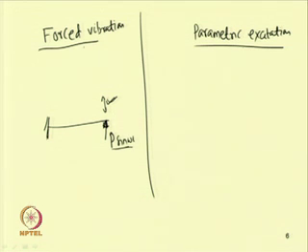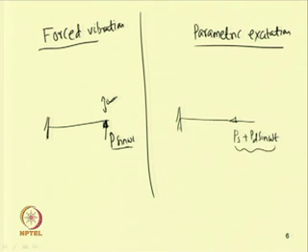But in the case of a parametrically excited system, let us take the same cantilever beam and apply an axial load, P s plus P d sin omega t. As we are applying an axial load to the system, if it exceeds the Euler buckling load, then it will start buckling. But when a dynamic force acts on the system, then for some value of the dynamic amplitude of the load and the frequency omega, it will start buckling before it attains the critical Euler buckling